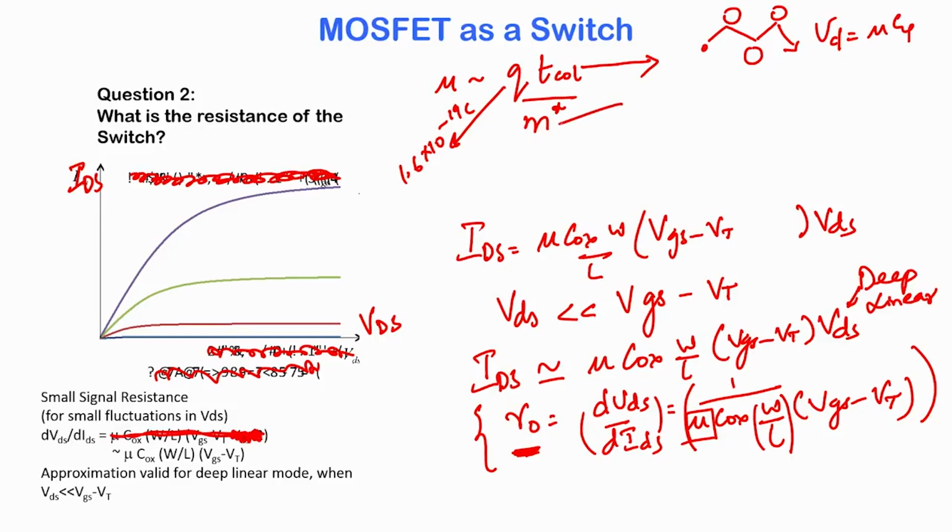What is the effective mass? The effective mass is dependent on the shape of your E-k diagram. You have an energy, you have a momentum or the k space, and let us say you have your E-k diagram. So, let us say that is the conduction band edge. We saw that the valley of this conduction band edge can be approximated as a parabola. Okay.